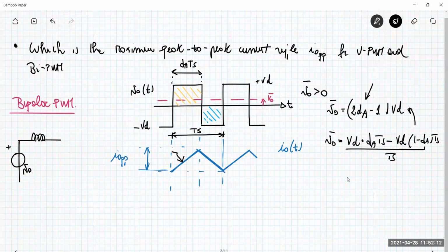Remember, the impedance of the resistance is just less than that of the inductance. This is not exactly correct because you also have this resistance, but it simplifies the computation a little bit. Then we have to consider no back EMF, because the back EMF is just a DC component. This is the AC equivalent circuit at the output.